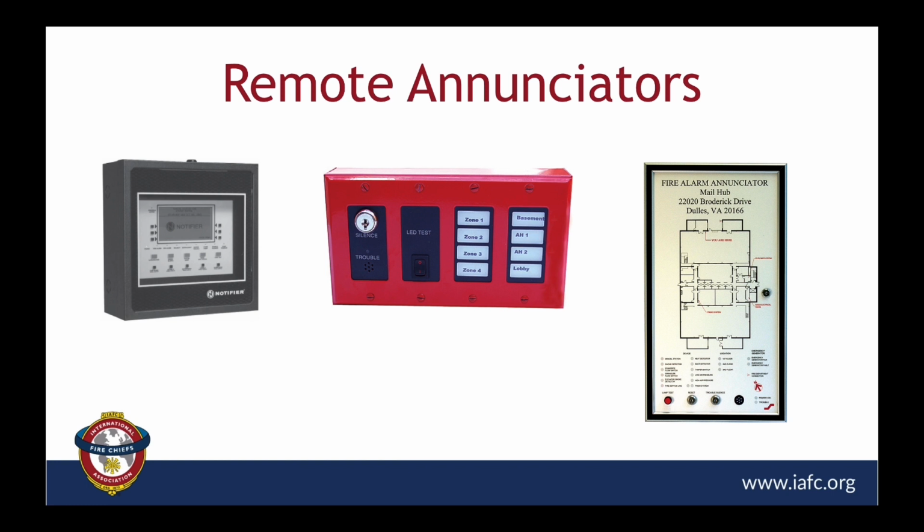The one in the center here is more of that conventional zone approach once again. Zones 1 through 4, it happens to be saying where those zones are right on here. Lobby, air handler 1 would be a duct detector, air handler 2, and then there's a basement. So this is obviously a lobby and a basement area, and this is letting you know as you walk in the door where the problem is originating from. You also have key switches here that are necessary to be able to silence it once again, and you're going to have to reset this one back at the control panel, which is most commonly the case.